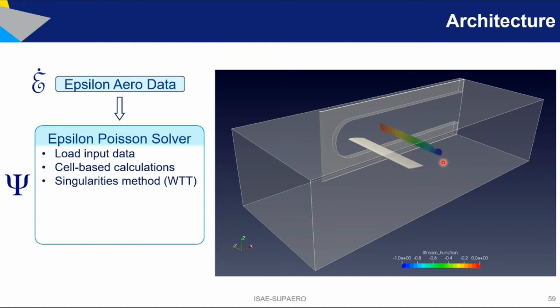That's my main objective, because I really want to compute vortex drag, and vortex drag is only a wake-reduced parameter, which requires computing the stream function at each point of the wake that has been measured during the wind tunnel run. And of course, these are all VTK operations that are embedded into the Python code.